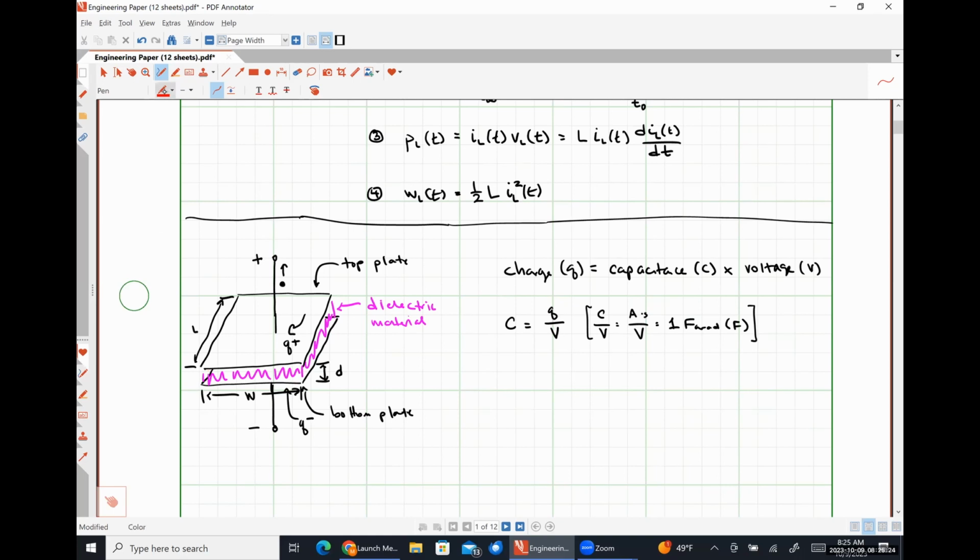we wind up getting, let me do it in blue, electric field lines oriented from the positive charge down to the negative charge. And sustaining this electric field is the energy storage mechanism for our capacitor. As soon as we no longer have that voltage drop across it, so if we were to allow it to discharge, the energy stored in the capacitor would slowly dissipate because the field would slowly get smaller and smaller and smaller until all of the charge moved off the plate. Okay.